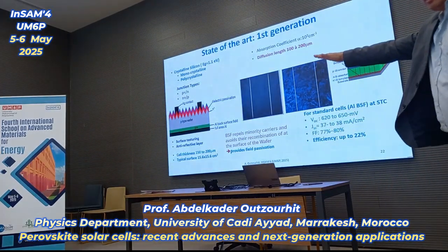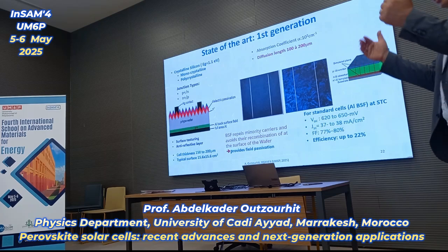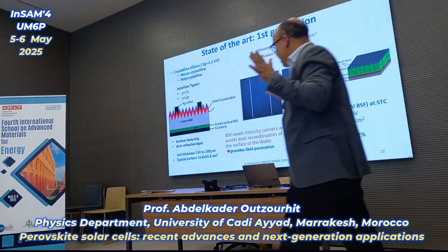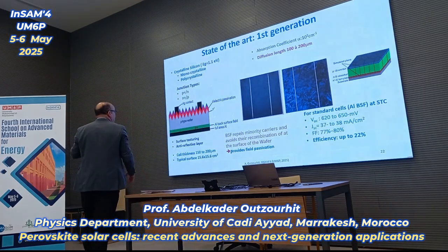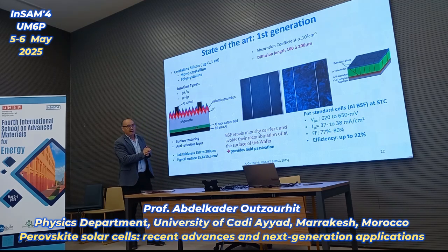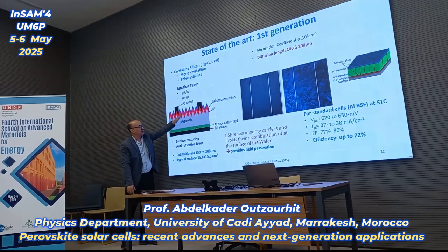As you can see, it resembles the theoretical solar cell I showed you in the beginning. So it is made of what? A P-type absorber. It's a silicon wafer, textured to enhance what we call light trapping within the semiconductor. Because if there are photons that are not absorbed, they cannot escape. They'll be reflected by these asperities inside the semiconductor. So this is a way to enhance light trapping. But anyway, it's a P-type, textured.